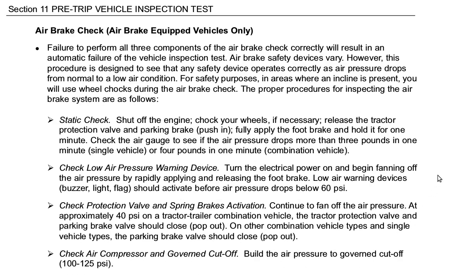Air brake check. Air brake equipped vehicles only. Failure to perform all 3 components of the air brake check correctly will result in an automatic failure of the vehicle inspection test. Air brake safety devices vary.